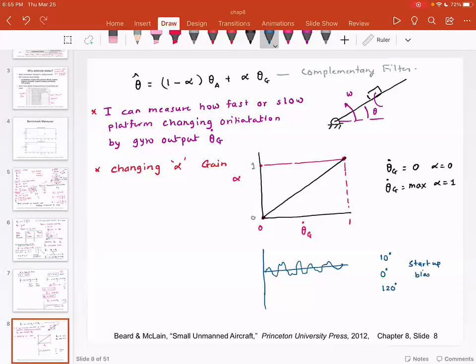Then you have something called noise. And sometimes you have something called thermal drift, which means as the temperature increases, the output of the gyroscope changes. So again, you have to calibrate it, but calibration would minimize, but will never eliminate these errors in typical sensors.